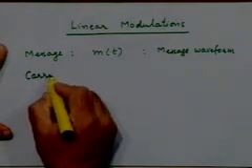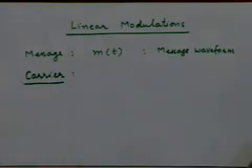The carrier, as we have discussed earlier, is typically a suitable high frequency sinusoid, right? The exact frequency will depend on the application. If it is a microwave link that you are working with, you will choose a typical frequency in the VHF or higher band. If it is the ionospheric propagation that you want to deal with, you will use a frequency less than 30 megahertz, something like your HF band. If you are carrying out broadcast using the ground wave propagation, you will use the medium wave frequency band. So depending on what the application is, you will choose your carrier frequency differently, but